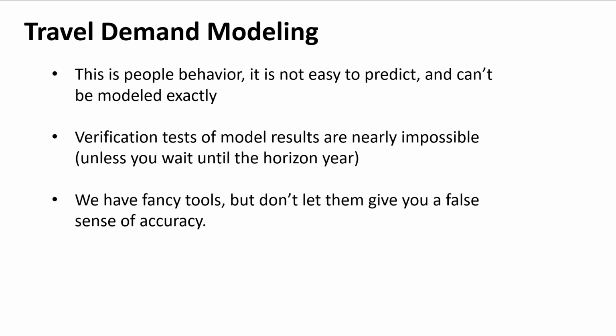And I've got this really fancy computer, and I spent $20,000 on this program. This thing is probably really good. No. It gives you an exact number like that, but what's the plus or minus? What's your error? Your error could be plus or minus 5,000 vehicles. So 17,521 sounds really exact, but that's plus or minus 5,000. Just keep this in mind: even though it may look like a pretty accurate number, it's a false sense of security. Just remember all the variables in here that you don't know when you're trying to do modeling.